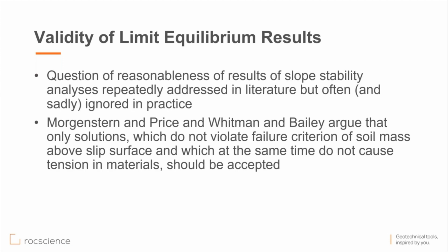And what do we mean by physically valid or reasonable answers? It means that we have to check, we'll get to it, the line of thrust, but it's extremely important. The methods for checking exist, but very often in practice, we do not check. And I hope that after today, all of us will make it a practice to check the results of our limit equilibrium analysis.